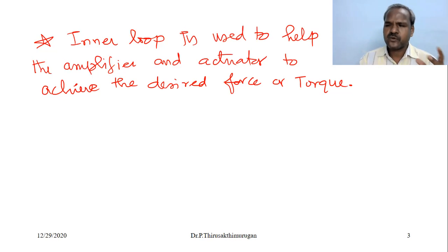Since the current is proportional to the torque produced by the motor, alternatively the motor controller may directly sense the torque by using a strain gauge on the motor's output gearing, and close a local torque control loop using the feedback. Understand or not?